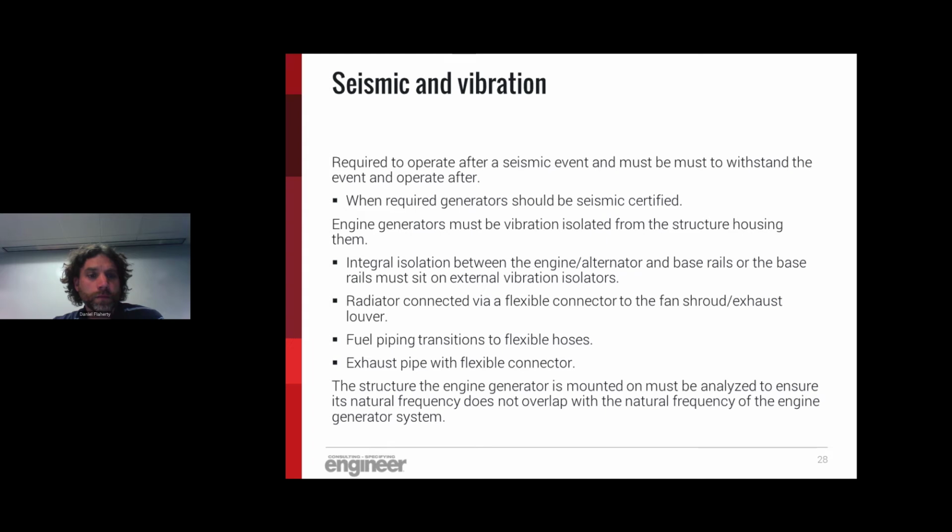Moving on to seismic and vibration. Where required, and usually this is done, you review ASCE 7 to see where seismic certification is required for the engine generators. Because engine generators, let's face it, they're there because something's gone wrong, and that something could very easily be an earthquake. So making sure that they're seismically rated is important.